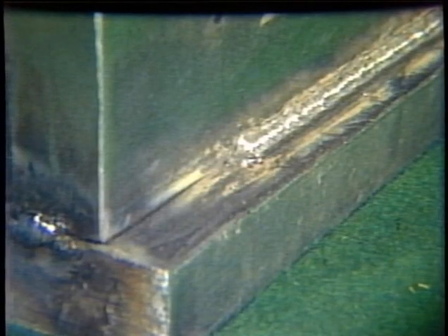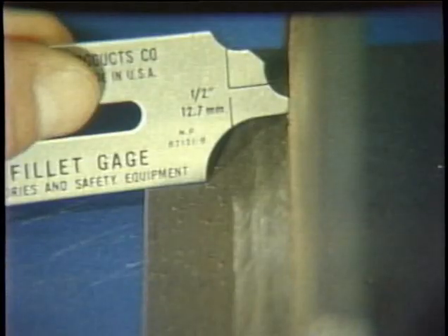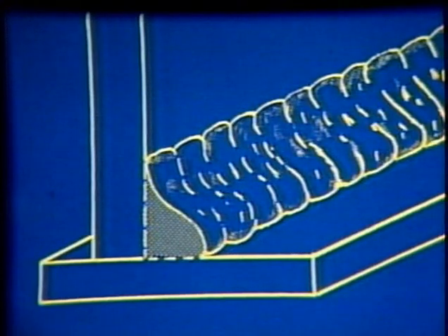Welds that do not meet the minimum size standard can be cause for unacceptability. Welds of incorrect size may be determined visually with the use of weld gauges or by comparison with approved workmanship samples. Incorrect weld profile is a common problem and is best described as a weld that does not meet the requirements for size or contour.